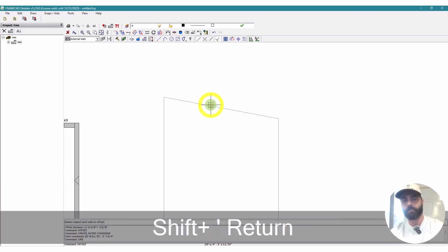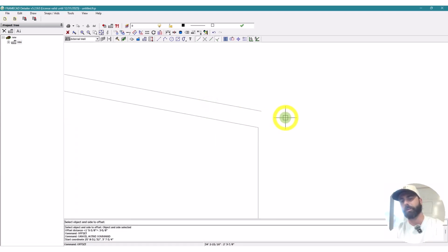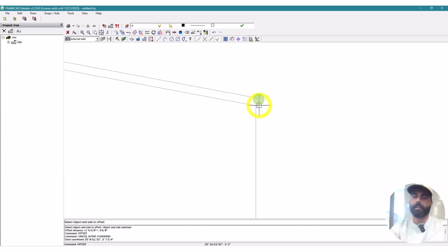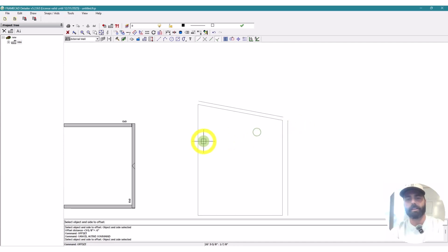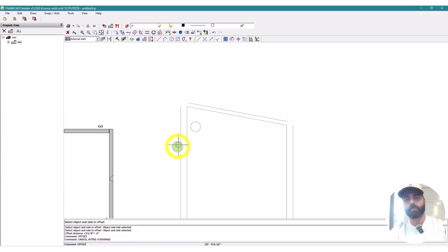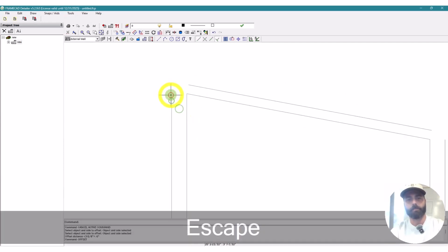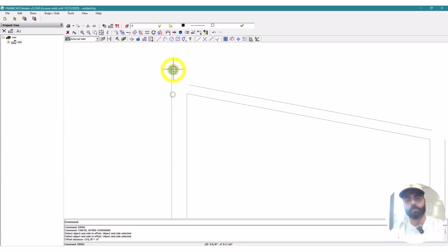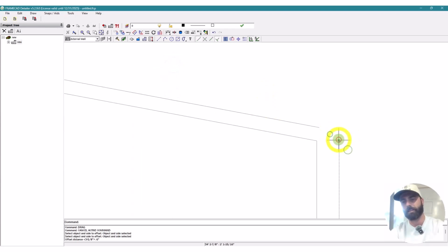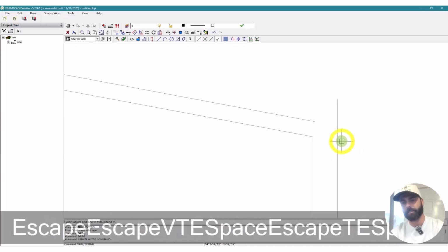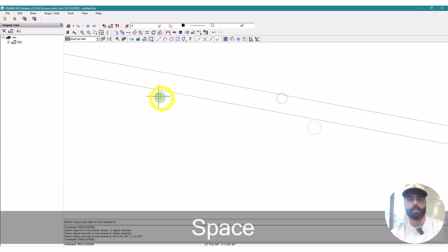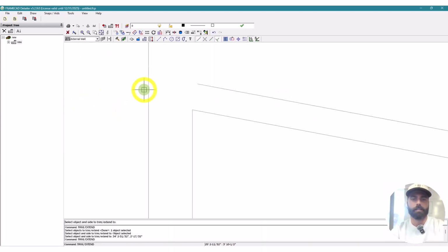I could draw myself a roof profile there. Do we want overhang or no overhang? Yes. Overhang? So we'll offset this 6 inches on both sides. I'll grab this wall here, trim extend this to that side, and then this one to this side.